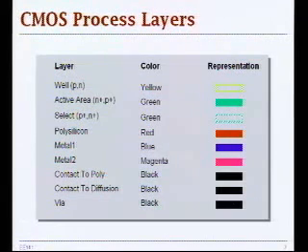So these are the layers, basically. That's the basic philosophy. As a designer, to do the layout, you have to assign each polygon to a certain layer that has some meaning in physical implementation. And then overlaying these polygons, you create your circuits.